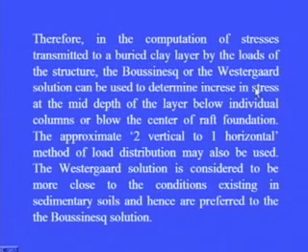Therefore, in the computation of stresses transmitted to a buried clay layer by the loads of the structure, the Boussinesq or the Westergaard solution can be used to determine the increase in stress at the mid depth of the layer below individual columns or below the center of a raft foundation. The approximate 2 vertical to 1 horizontal method of load distribution may also be used. The Westergaard solution is considered to be closer to the conditions existing in sedimentary soils and hence is preferred to the Boussinesq solution.